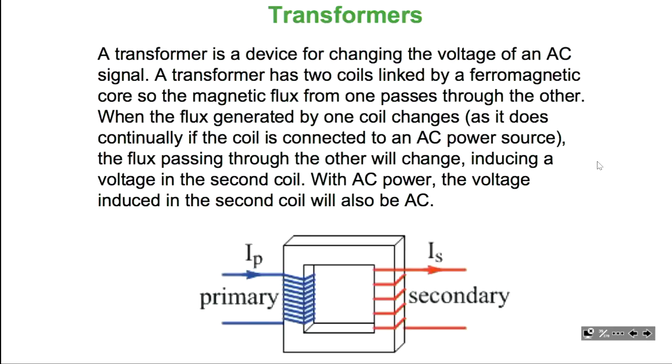But now, because I go from 800 to 400 turns, I should read 7 divided by 2, 3.5. But there's additional loss, 2.8. That's how a transformer works. And the easy solution is just break everything down.